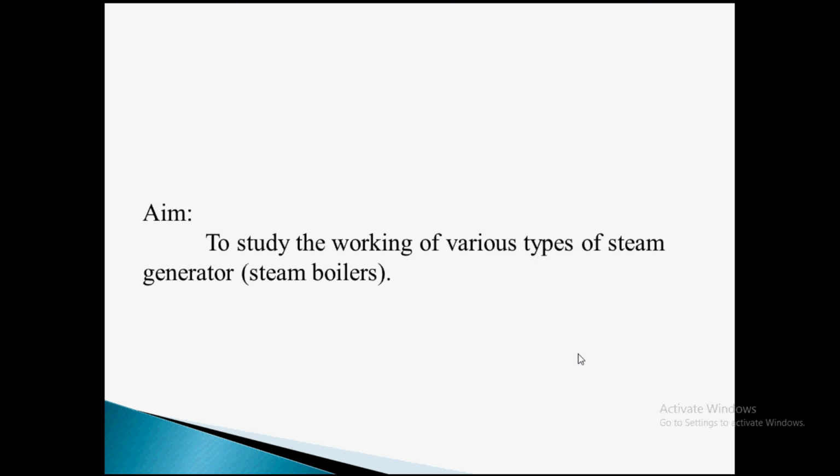The arrangement is shown. The most sensible heat is supplied to the feed water passing to the economizer. A centrifugal pump circulates the water, equal to 8 to 10 times the weight of steam evaporated, through the tubes and the part of water supplied to the drum. The large quantity of water circulated prevents the tubes from being overheated. To secure the uniform flow of feed water through each of the parallel boiler circuits, a choke is fitted to each circuit. Next, BHL boilers.